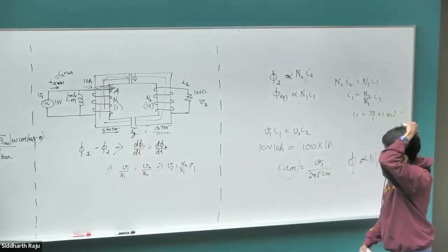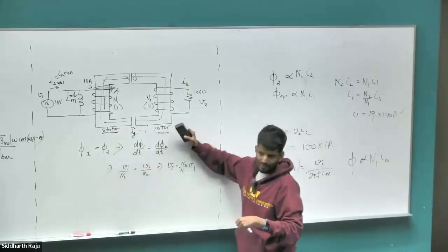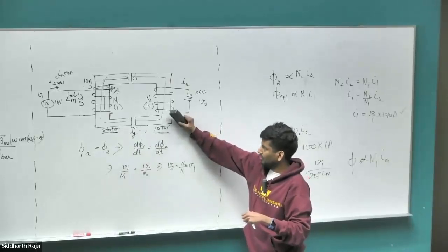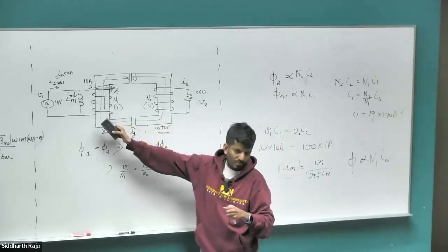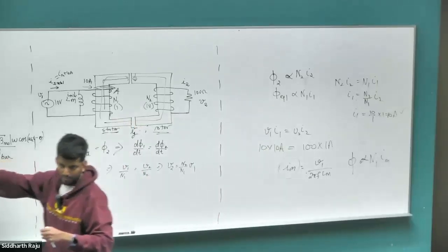So, coming back to this case, we have the exact same setup here. We have our stator here, we have our rotor here. There is a current going in the rotor. It tries to establish a flux on the rotor in the air gap, but that flux is instantaneously cancelled out by an equivalent current drawn from the stator. The same thing would happen for an induction motor.